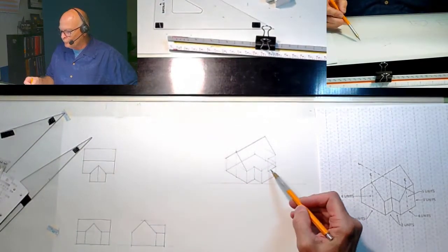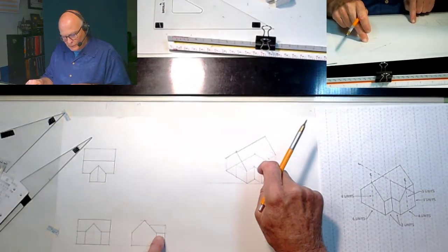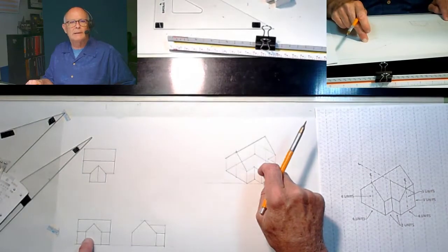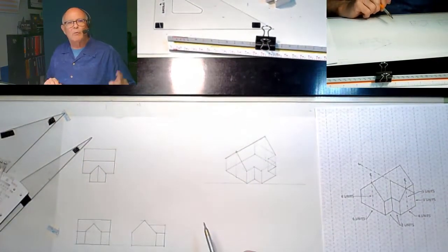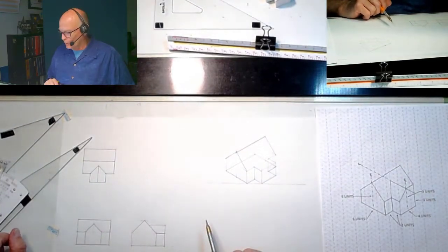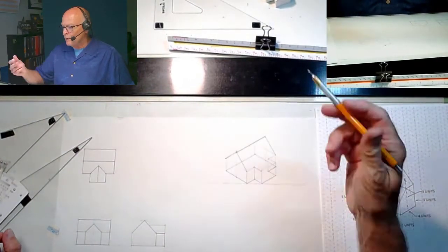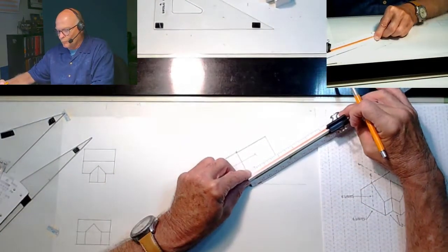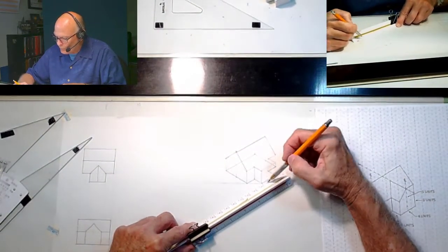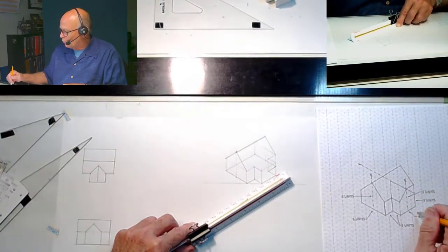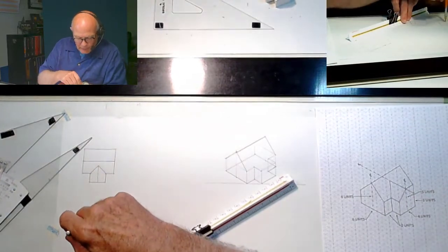Now we need to spruce up some of this here by adding in the front element, this front gable, or this front roof line. So how do we do that? Well, we're going to do the same thing we did before. Remember that it's a horizontal line, so it's going to be at 30 degrees. And how do we find it? We're going to come over to the line. Let's see if I can do it this way. It might be easier for you to see. We know that that's 4. It says that that's 4, and there's a center line, so that's going to give me 2. Same thing that happened right here.